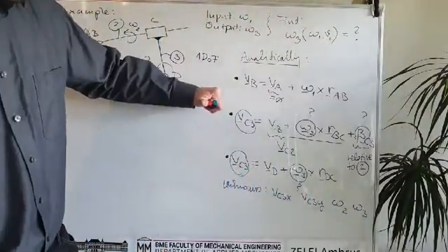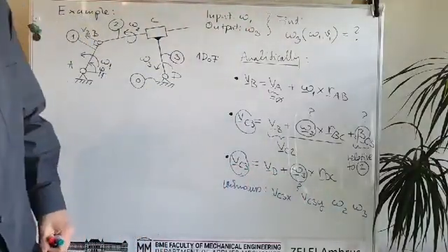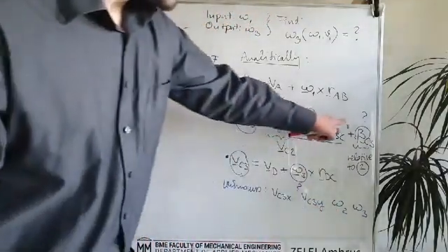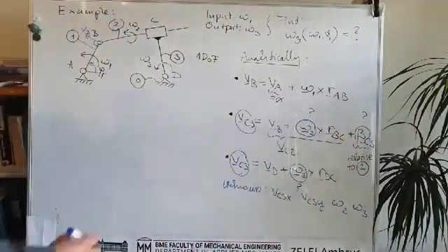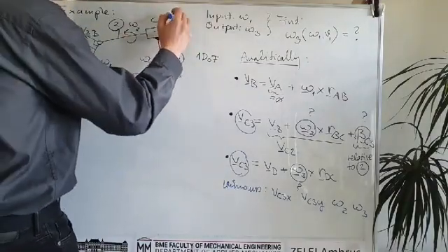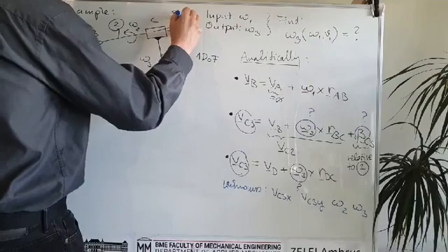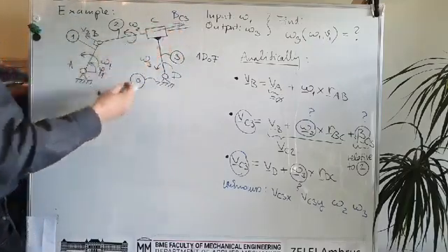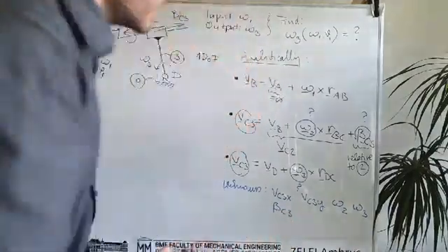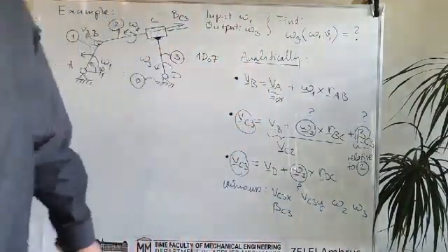The direction is well known because they are perpendicular to the whiteboard, but we don't know the magnitude of them. And the direction of this relative speed is also a known thing. So beta C3 has this direction, but the magnitude again is unknown. So the BC3 scalar variable is unknown.